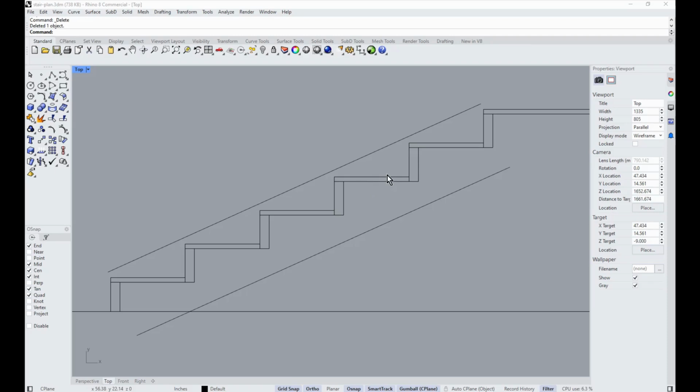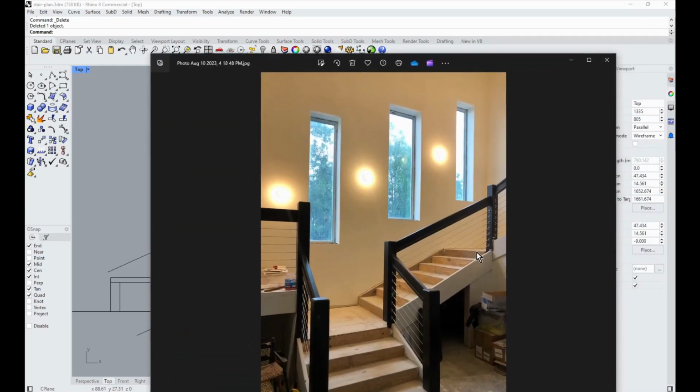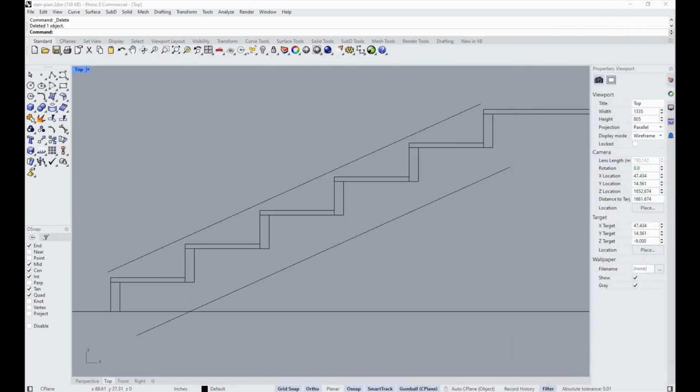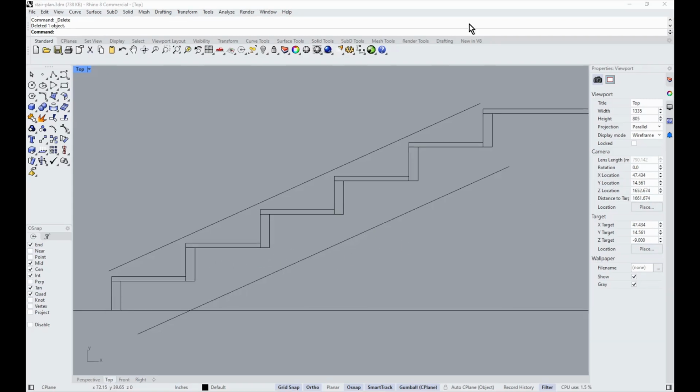And you can see here, if we made these treads out of 2x12s, first of all, the length would be 3/4 of an inch shorter, and it would start getting really thin right here. That's why these skirt boards are good to use on the side. Now you can keep an end open on the ends. It's all up to your style and what you're trying to go for.